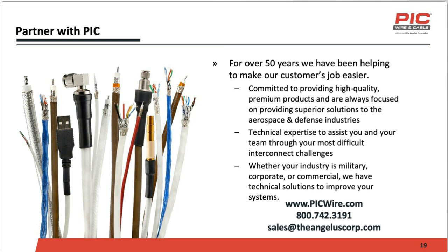It's really quite simple. First you just thread back the back shell, and then you can pull out the HSM by pressing the tabs together. The HSM will simply come out of the back shell. Then there's a captive screw that you loosen up, which will release the cable, and then you can pretty much pull out the individual 22D contacts and repair them on an individual basis as needed.